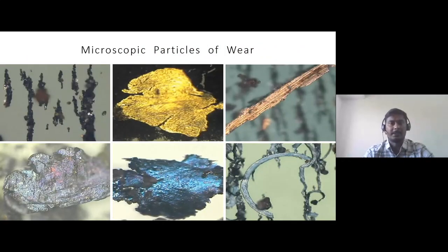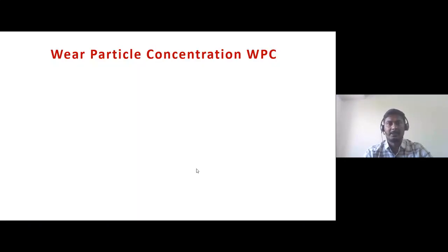This looks like normal rubbing wear, this is copper, medium alloy steel, gear wear, bearing wear and cutting wear. We can understand these particle types in the microscopic view, so we can say which type of failure is going on, whether it is contamination, no lubricant, or a feed rate increase or decrease.